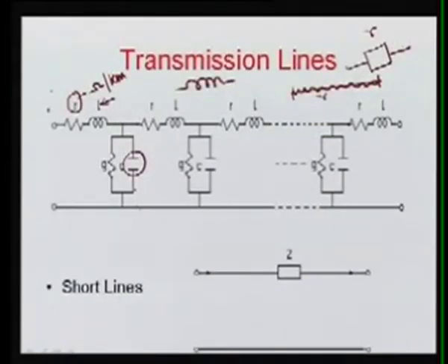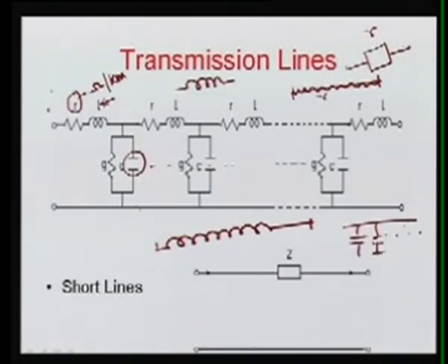The capacitance is due to the charge on the conductor, and between it and the neutral point there is a potential difference, and then we form the capacitance. So, we have this L, that is inductance, and the capacitance formed, and they are distributed, meaning in every smaller section the inductors are distributed throughout the length of the line. Similarly, the capacitances are also distributed in nature.